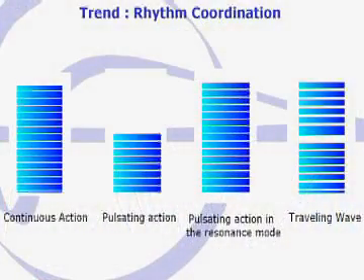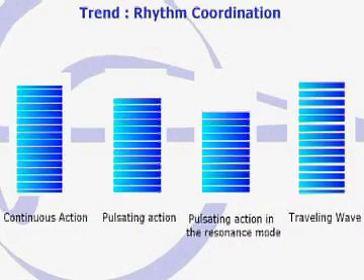And so what this trend will tell us to do is add some kind of pulsation to the system. The trend tells us somewhere there will be a benefit in moving to the right along the trend. And in this case, what we find is if we pulse the water jet going into the bottle, we can reduce the amount of water we require by about 50%. A substantial improvement for a very simple change to the system. But the trend says there are still more stages here that you've not used yet.